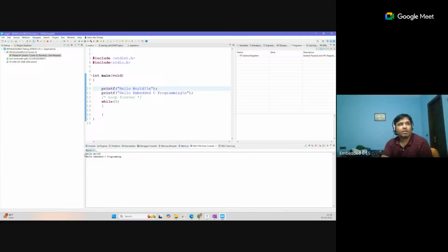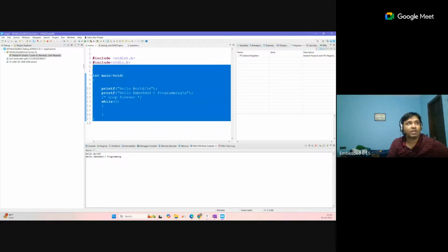Okay, through the debugger. To see some experiments, we have these input output pins. We want to give some input through one pin, and we want to see some output through a pin. That experiment we can see through some indication on the board, like we can connect some LED. When we press some button, that LED will turn off. That code will be written based on our purpose and uploaded on the board, and the board will perform the function according to our program. Okay, so we will see in the coming sessions how we can connect the things.